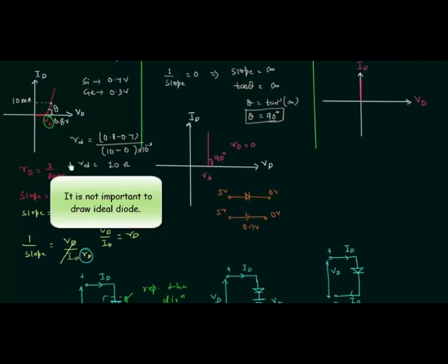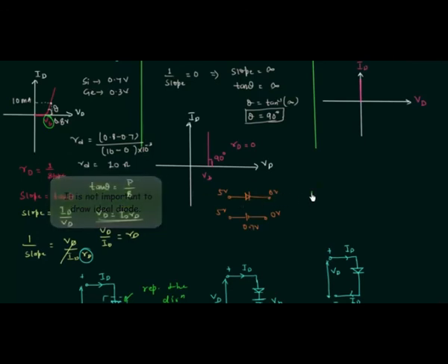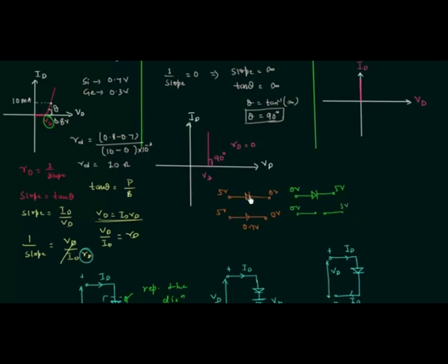And if the diode is reverse biased like this, this is 0 volts and this is 5 volts, P side is connected to the low potential and N side is connected to the high potential. So this is the reverse bias condition. And in case of reverse bias condition, there will be no current through the diode, so it will act as open circuit like this. These 2 points are very important, and by using them we can easily solve the numerical problems. In forward bias condition, you have to replace the diode by its barrier potential, and in reverse bias condition it will act as open circuit.